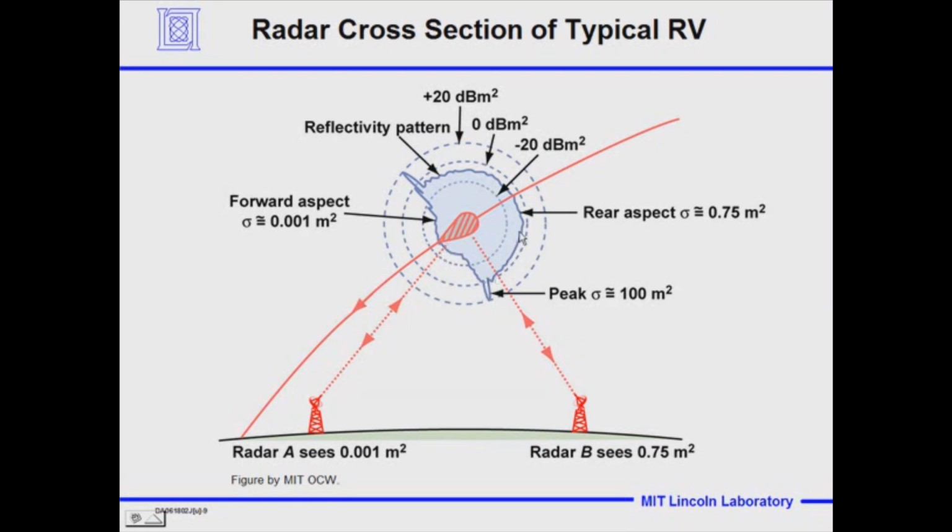And here we see this blue line, and this polar plot is the radar cross section of it. Here's the trajectory of that reentry vehicle coming in. In the forward direction, the cross section that you see is 1,000th of a meter squared. Wow, very, very small. And then as you go out an angle, and you look at this side region here, this specular region is huge.